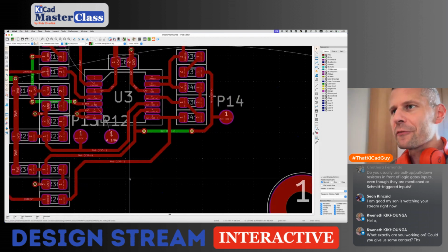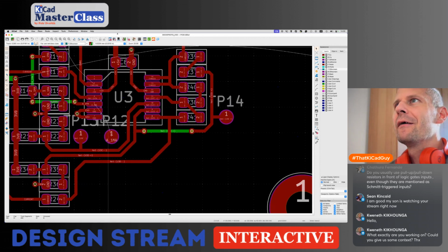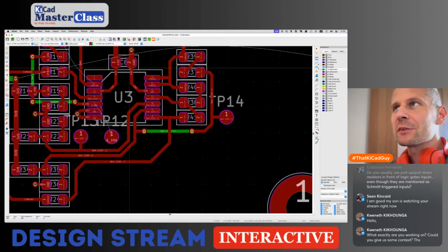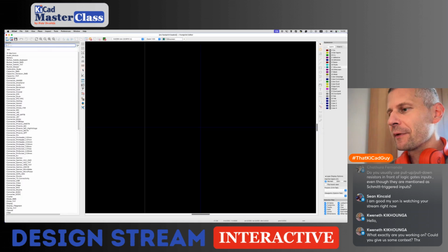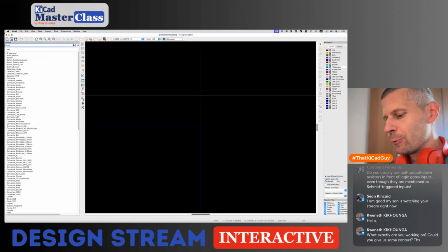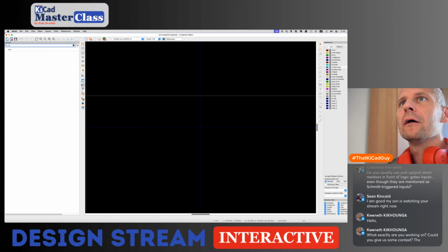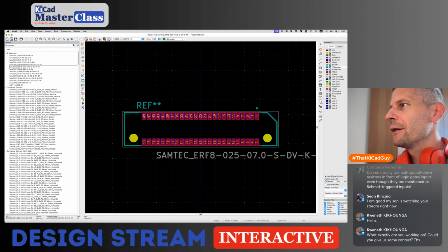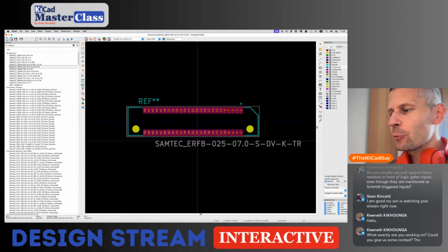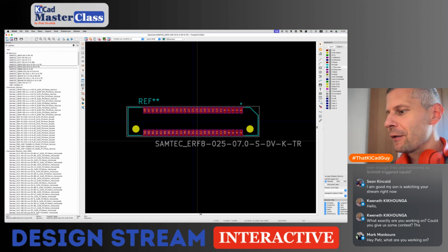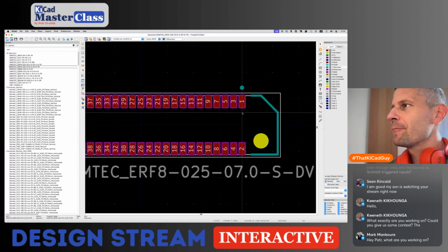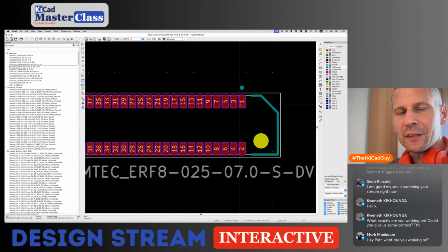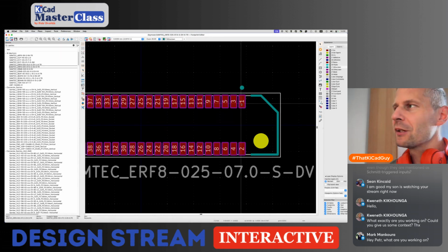As a bonus to all of you, I found today a cool function of the footprint editor. Let me show you. When you open a footprint, and I downloaded this footprint from the web, they numbered the pins with the leading zero notation. So instead of 1, there was 01, 02, etc.